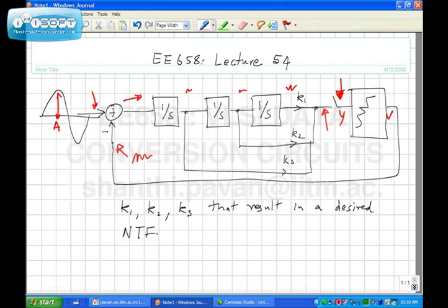What the question is raising is, if this is almost equal to the input plus shaped quantization noise, what should the signal going in be? This is input plus shaped noise. So when you subtract the two, what goes into the loop is shaped noise. But if you just put in noise, you can't expect signal to magically develop here. So how is that happening?